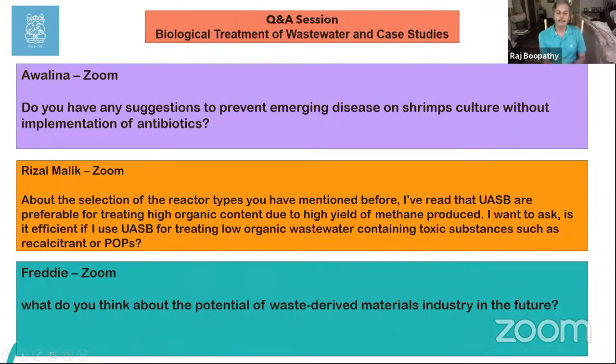Yes. You have to have this carbon nitrogen ratio. If your aim is to remove POPs in your wastewater and any other toxic substance, but it starts with low COD, you need to provide some carbon to keep your bacterial number high. For example, in my denitrification step, I ran out of carbon, so I had to add molasses to the system. So you have to watch your carbon nitrogen ratio in your system. In wastewater, generally a 30:1 ratio is what they follow, sometimes 20:1, depending on the wastewater. So for every 30 parts of carbon, you need 1 part of nitrogen.